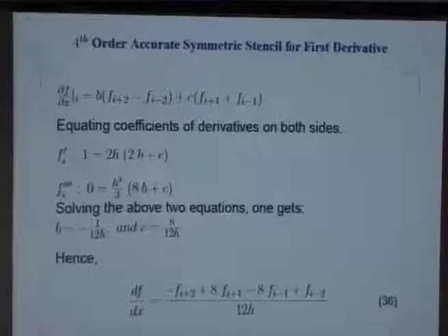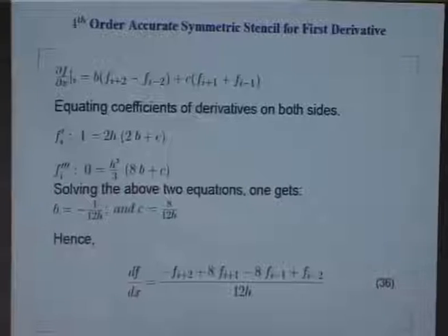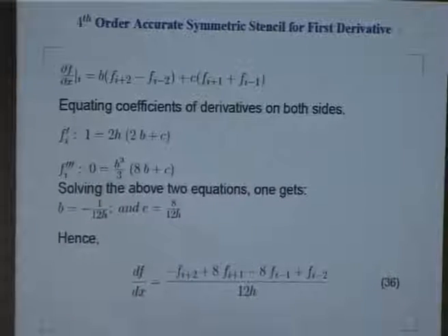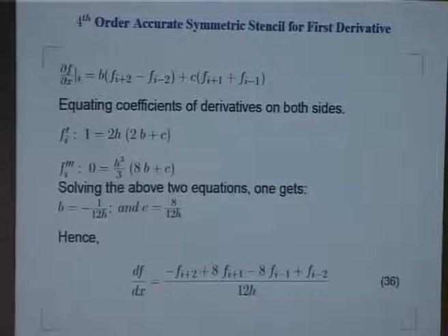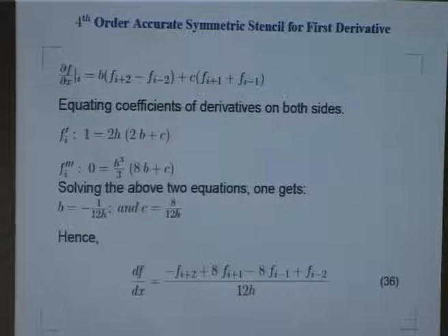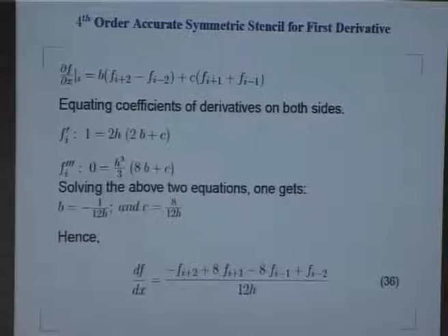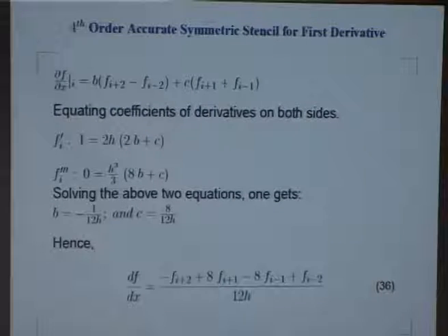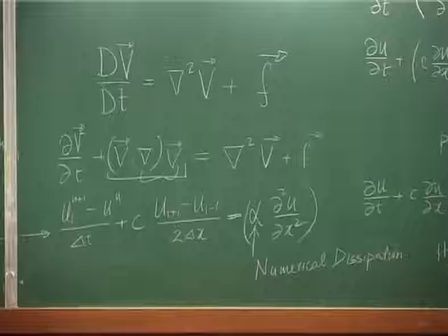Yeah. So, we have a fourth order accurate representation of the convection term, and again you will notice that keeping it as a Euler time discretization with fourth order central differencing of the kind given by that equation 36 will still make the method unstable, right, will still have an unstable method.